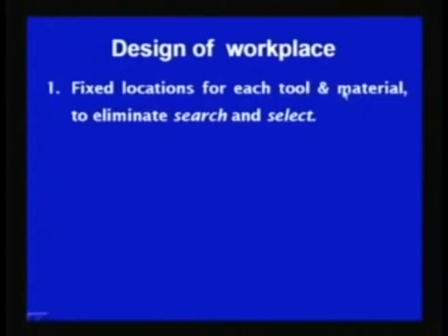The workplace should be designed keeping in mind certain aspects, like fixed location for each tool and material should be provided, so that it will not require unnecessary searching and selection related steps, because a lot of time is consumed in finding the desired item and then getting it for carrying out the further operation, either assembling or further processing of the raw material or using the tools for further processing.